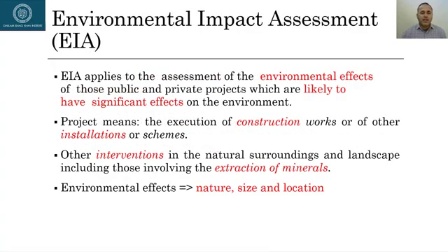Now, EIA applies to the assessment of environmental effects of those public and private sector projects which are likely to have significant effects on the environment. The purpose of this bullet point is that in countries like Pakistan, environmental impact assessments are not done for each and every project. They are done only for those projects which may have significant effects on the environment.